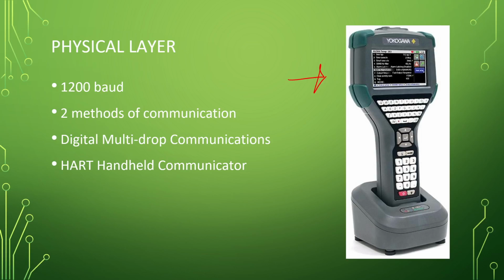And then this could do some polling as well. So you could go, hey, give me this information, and the device would then respond to you. So this is a really nice device to be able to just pop in there and read sensor values. Anywhere you can connect this thing to the wire, you could then get information off that HART network. So in that aspect, it's really nice.